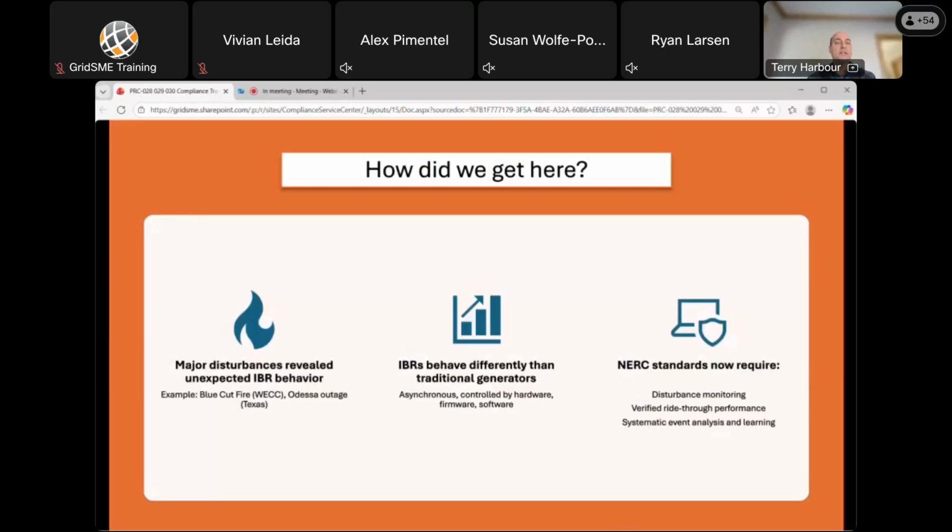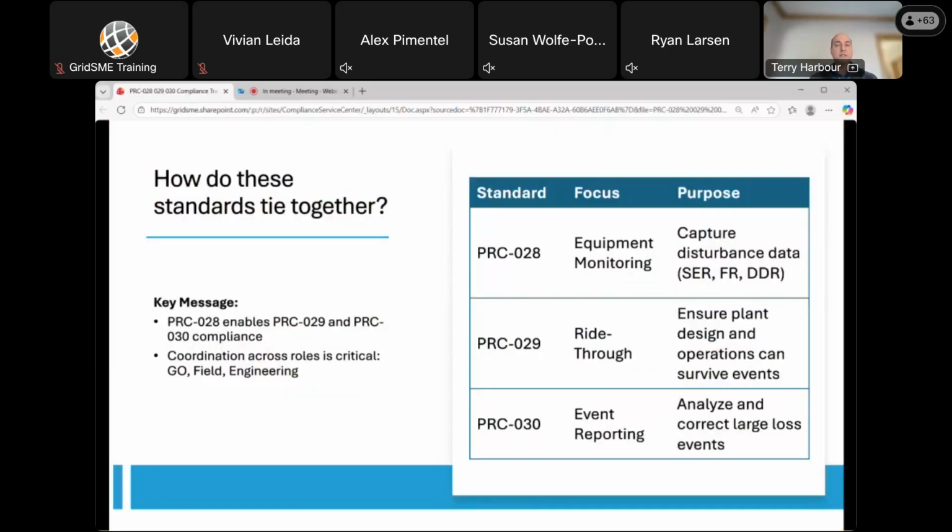As far back as 2016, NERC began identifying inverter-based resource events and developing reports, and that inverter-based resources were a little different. Unlike synchronous rotating generators, which are magnetically coupled to the grid, inverter-based resources are asynchronous, meaning they're more predominantly driven by their controls and their protections. That doesn't mean they don't interact with the grid. It just means those controls tend to predominate.